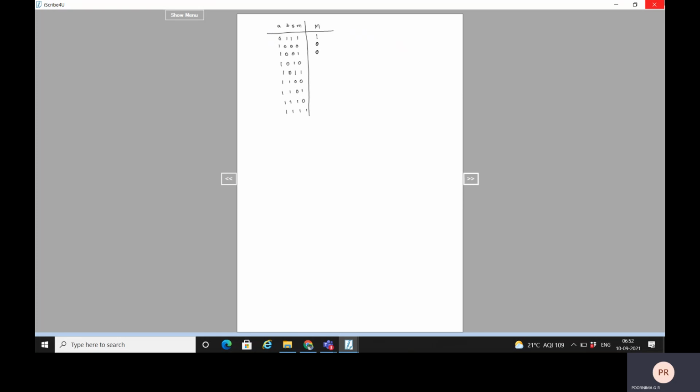Switch is closed. In the next combination, an operator exists but material is not there, so the motor should not turn on. The next combination, one operator, the switch is closed, material exists, so therefore here we need to make the motor turn on.